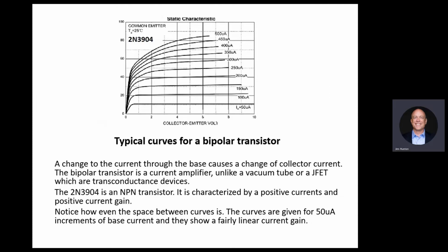Bipolar transistors, because they conduct, have more inherent internal resistances than the MOSFET. Resistance, we will see, is a source of noise. So usually you don't see them in extremely low noise circuits. There are some bipolar transistors that are good in that sense. They were manufactured specifically for low noise, and they improved the resistances inside the device.